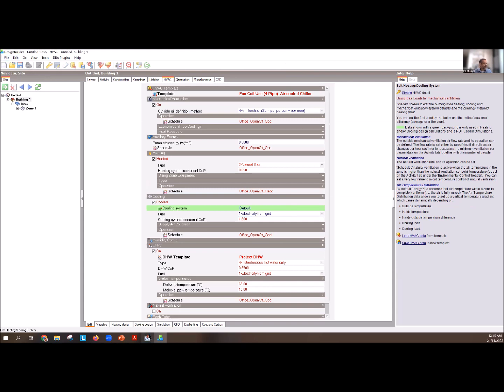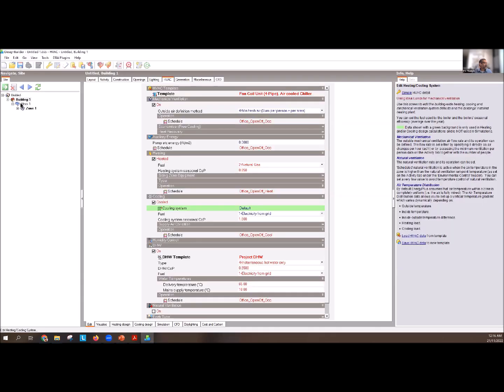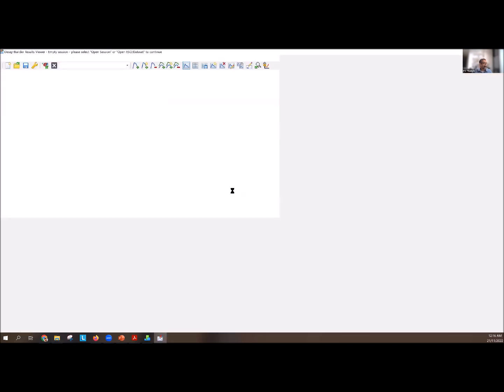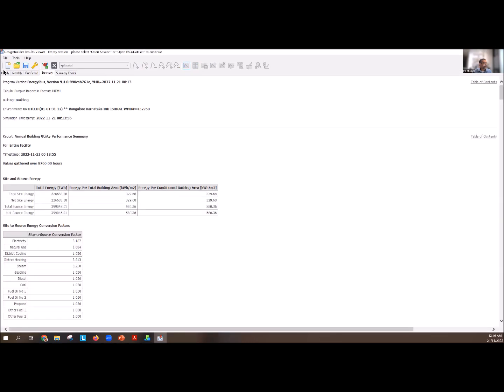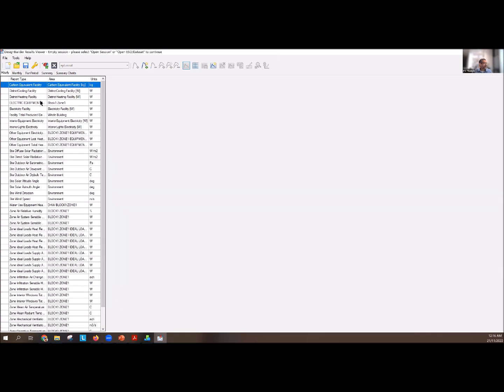If you go to that ESO file we were looking at, so if I go File, Folders, Energy Plus folder, ESO file, and when it comes up, there are two variables there that are quite useful, especially when you are running it using ideal or simple air conditioning.